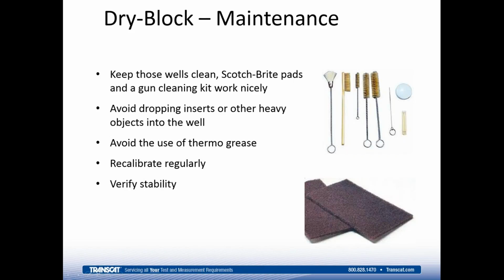Finally, I want to talk about dry block maintenance. If you want to keep that dry block working nicely, you want to keep it clean. You guys are probably the choir here when we talk about maintenance, that it's an important thing to do. If you don't maintain your dry block, pretty soon you won't be able to put the probes in it anymore. The performance may degrade, that sort of thing.